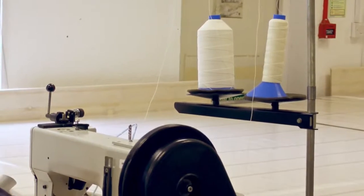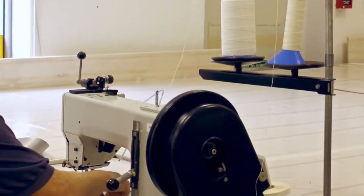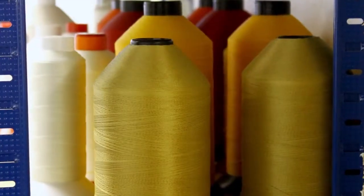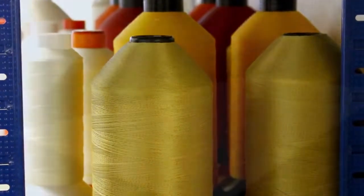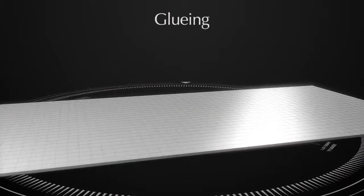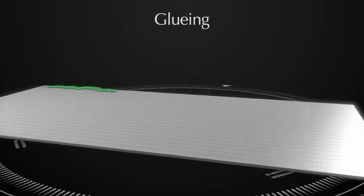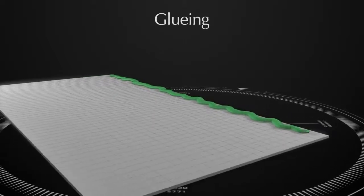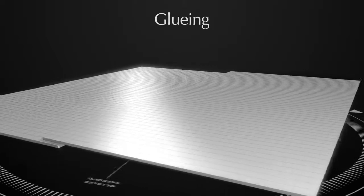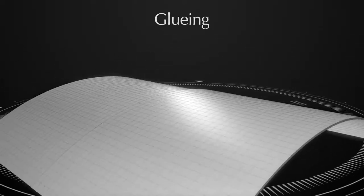Sewing is suitable for smaller projects, and for reinforcement patches on some larger membranes, we use industrial sewing machines and UV-stable thread to join the fabric layers to one another. For some applications and some types of fabric membrane, including silicon-coated glass cloth, welding or sewing are not an effective means of joining. Gluing using a high bond adhesive will provide a joint with adequate strength and durability.